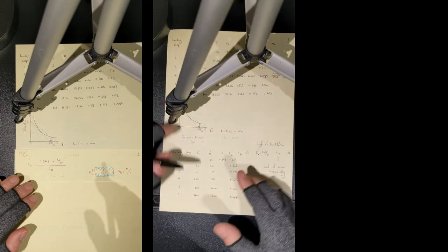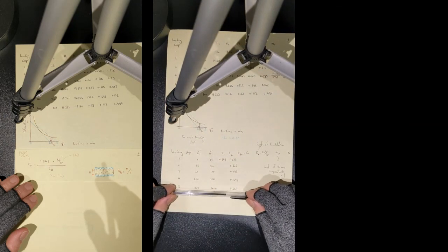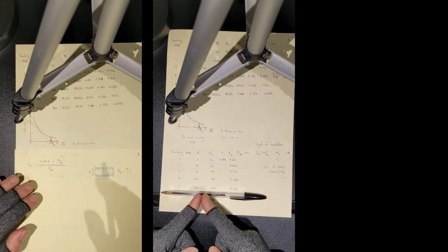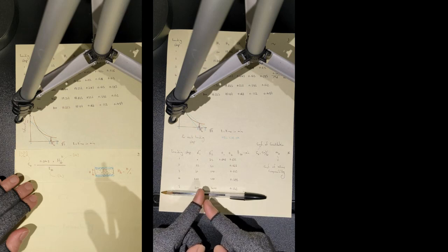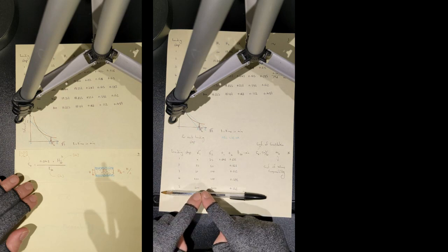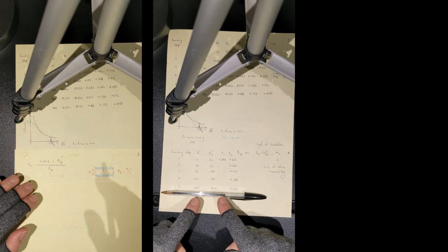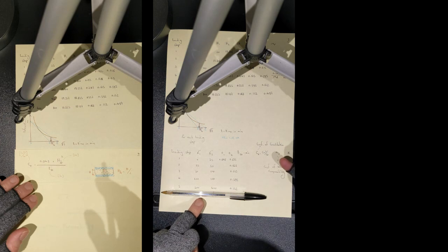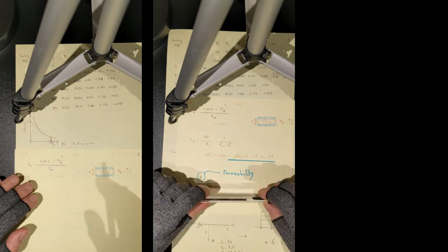Okay, let's see. So I'm moving from 250 to 350. So I'm in this range. This is the range valid for 200 to 400. I'm moving from 250 to 350. So my loading step 5 kind of matches what I'm looking for. So if I can determine the M sub V for loading step 5, this M sub V value can be used in determining my consolidation settlement.